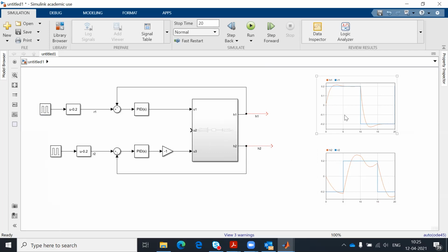So now we are controlling both levels. And you might ask why a PI controller, why not P? For the second one, P might also work, but we may have some disturbance as well, and the disturbance could be a leakage or an evaporation, let's say if we have the tank outdoors. Because of those disturbances, a PI controller can take care of those issues as well. I'm not going to convince you why PI or something like that.